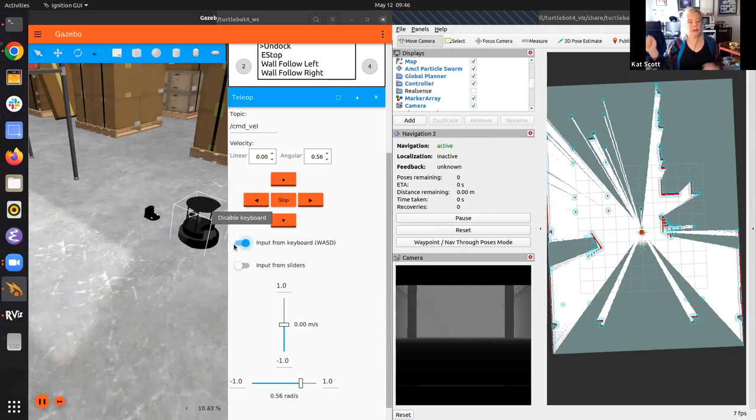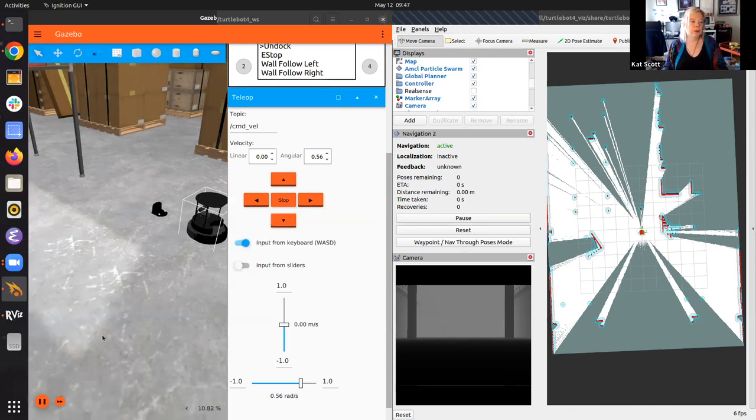They need to model all of these different hydrodynamic properties about the vehicle, and they might want to add in tides and what they already know about currents. You can do that in Gazebo. You can take all that information and start building a model and try to train your robot from there, or build the simulation to run your robot in.